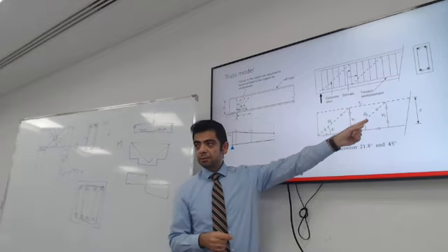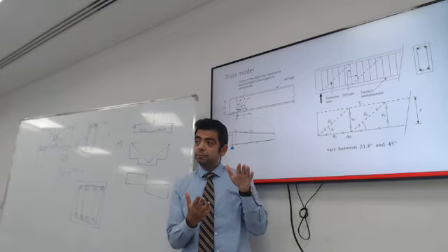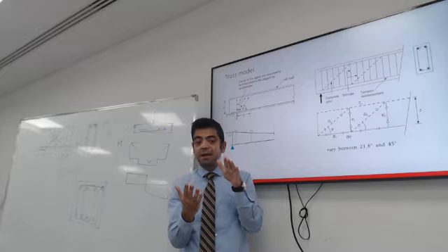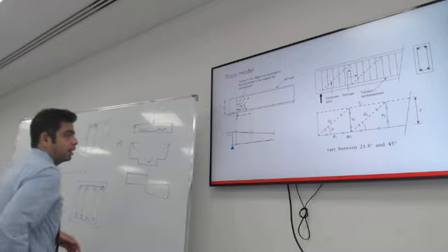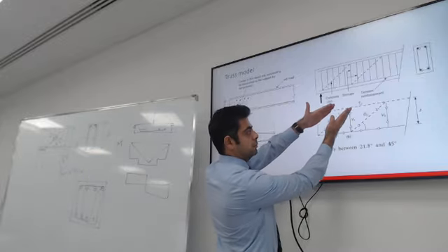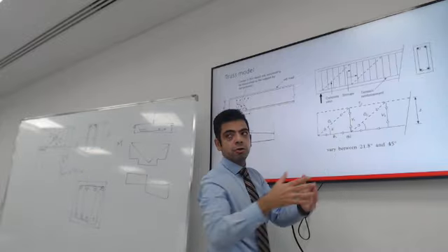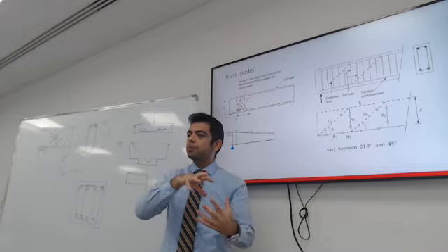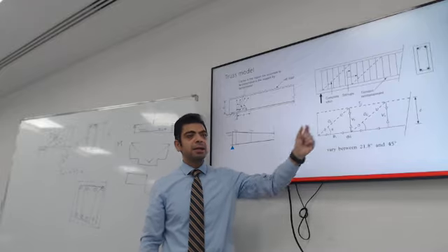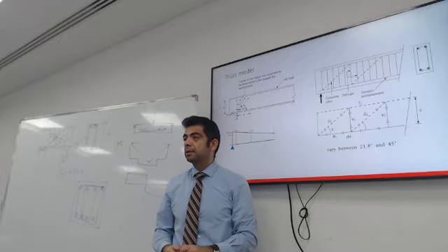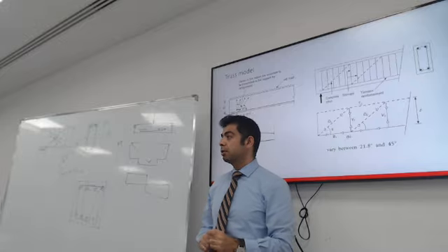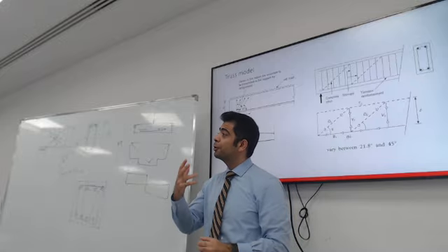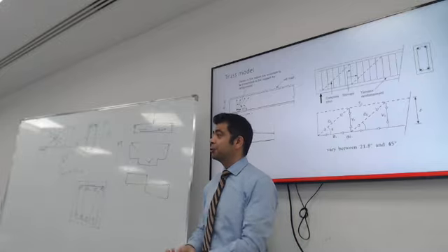The concrete in between this area is going to form a strut that will resist this compression force, because the dotted line is compression. The solid line is tension. All right? Very interesting model to understand how shear works its way and how to resist it.